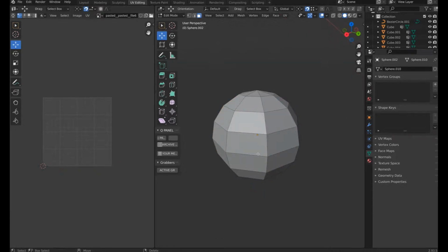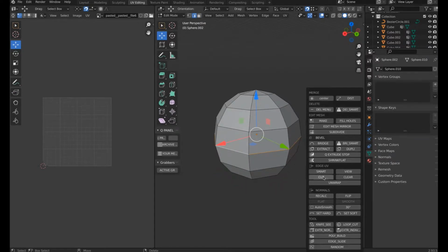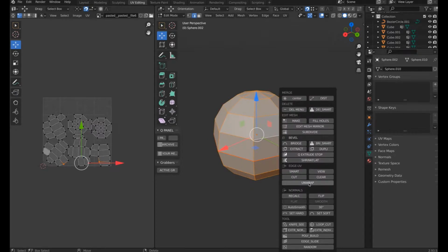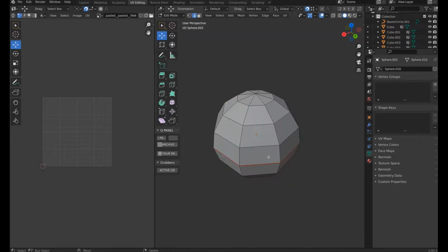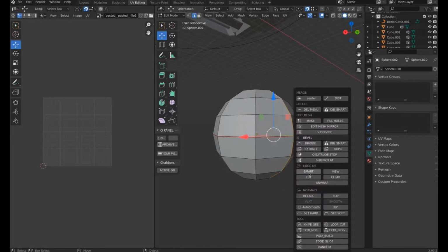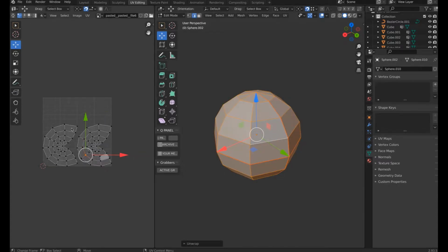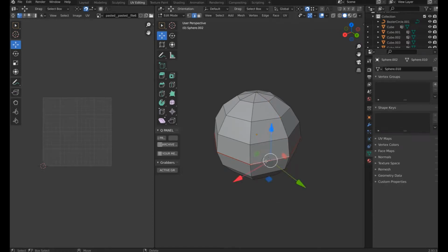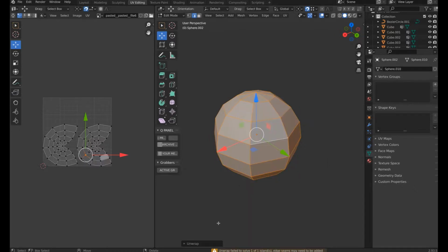But what you really want to do is select some edges on your mesh and apply a cut. Do you see the edge change color? And now, when you ask for unwrap, Blender will unwrap the mesh based on the cuts you made. So, if you cut over here and apply another unwrap, do you see the changes? You can also clear the cuts, but if you don't have any cut, unwrap can't be made.